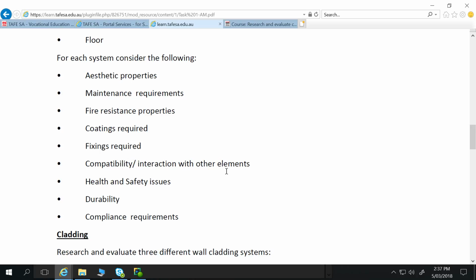Health and safety issues, well, that's generally specific to the material. So we all know asbestos, certain health and safety issues with asbestos, and hence we don't use it. But I guess lesser known, MDF, medium density fiberboard, there are issues. What's that? That's the next asbestos. Yes, I've heard several people refer to that as the next asbestos. It's tiny little fibres, when you're cutting it, you've got to really wear masks, etc. Or even hardwoods. People get lung cancer who have worked with hardwoods a lot from breathing in the dust and things like that. So we've got some health and safety issues in working with the materials.